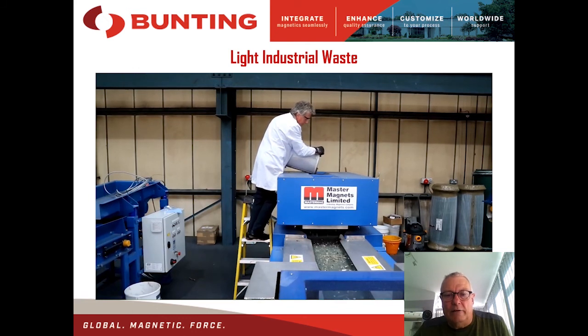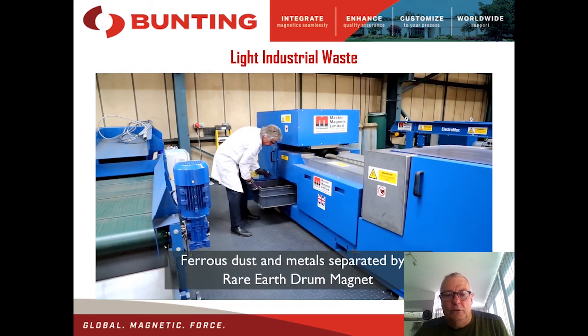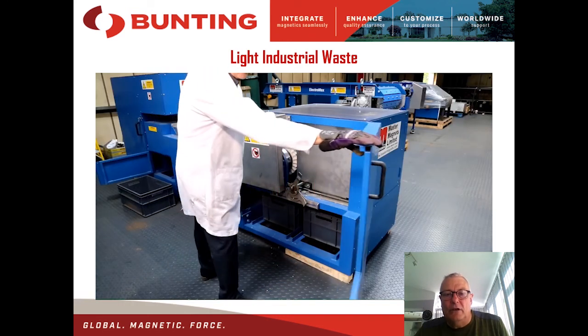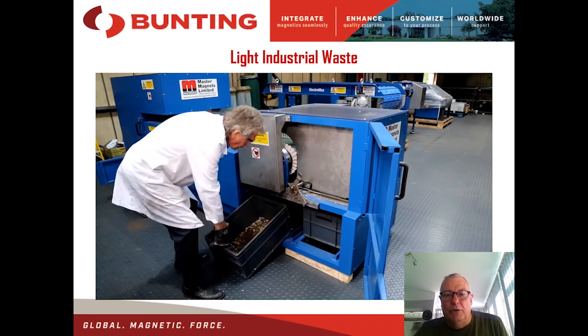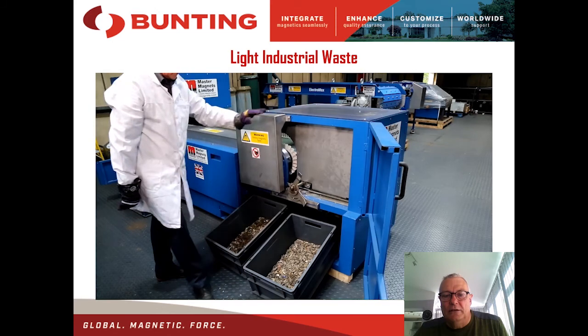eddy current separator here. Phil Tree is putting material over the rare earth drum that you see there, and that's the magnetic fraction from the rare earth drum. It's gone over the front pulley. There you see the pulley splitter plate position here. This is the non-conductors, and this is the conductors here.